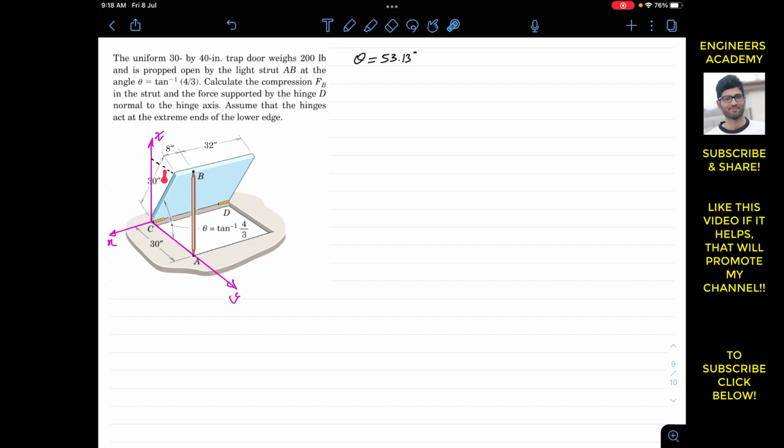This is given. So if this angle is 53.13, then this length along the z-axis is 30 sine of 53.13, and then this length is 30 cos of 53.13. Now why are we finding these dimensions? Since we want to find the coordinates of point B and point A, since we want to have the Cartesian vector representation of FB, which is the force applied by the strut.